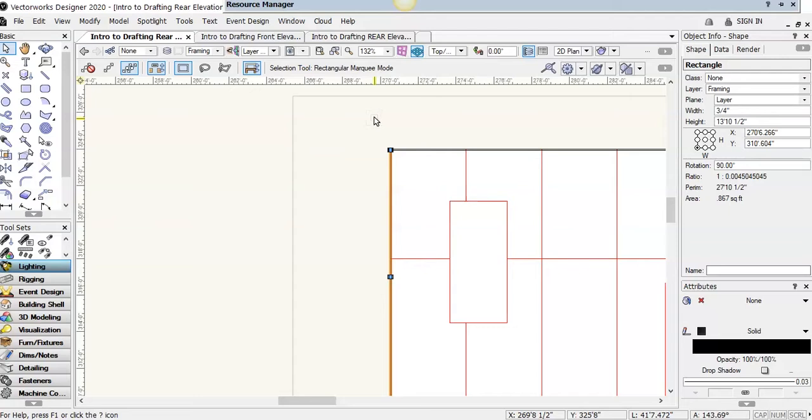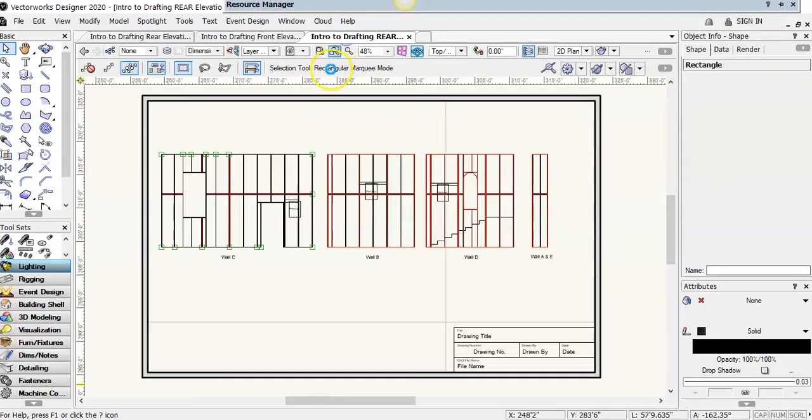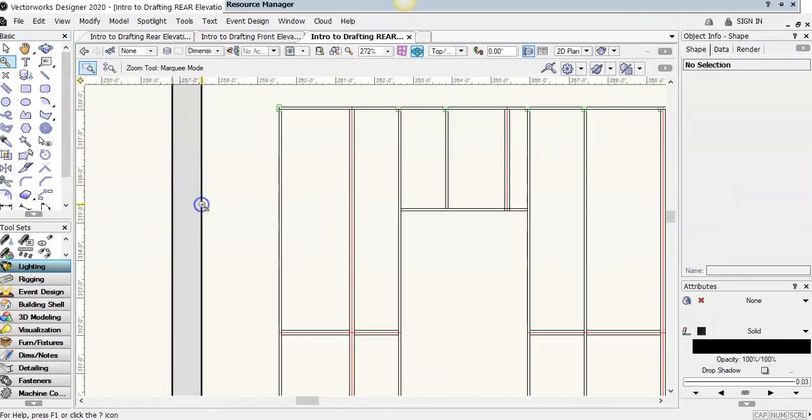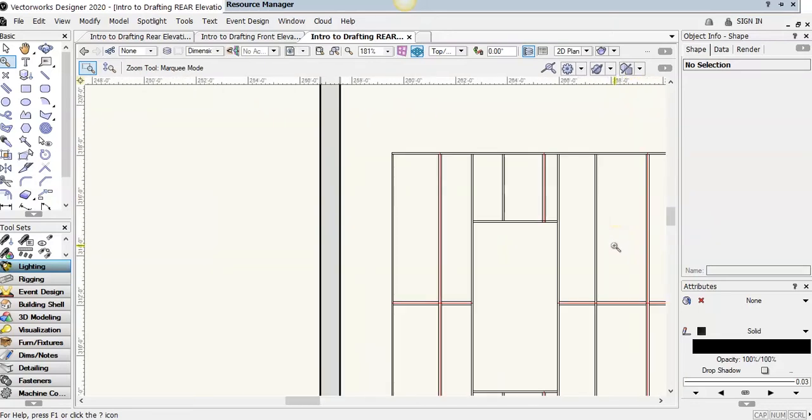So depending on how the wall is going to be used, that's how many vertical studs you'll have in there. I'm going to look at our finished drawing and zoom in just a touch. Okay, it looks like we are doing, depending on how things lay out, generally a 2 foot spacing.